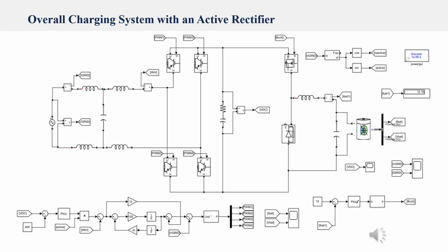So we have our DC link over here, in the middle of the circuit, to smoothen or to remove ripples from the DC and give us a very straight signal. This signal becomes our main DC, and then this is used to charge the battery.